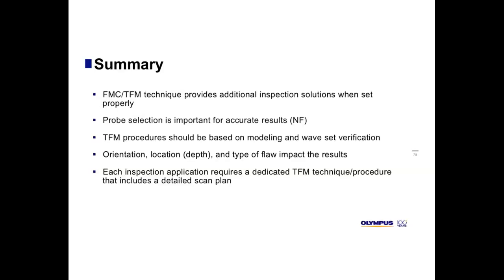Each inspection application requires a dedicated TFM technique or procedure that includes a detailed scan plan. As we saw, the scan plan is very important, and it should be specific to one specific project or application. It can't be used for any inspection.